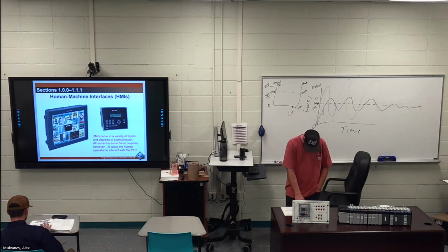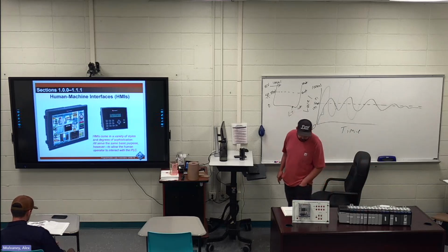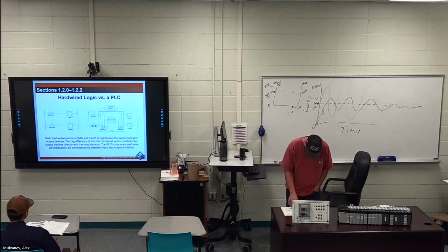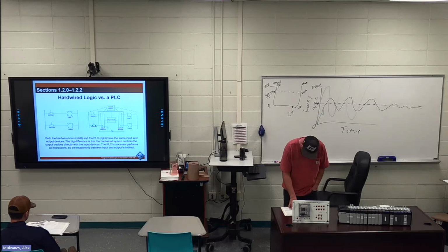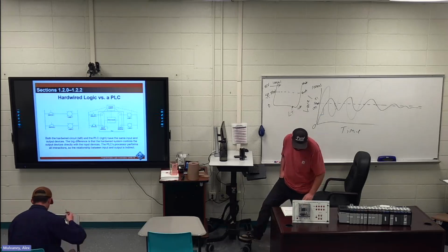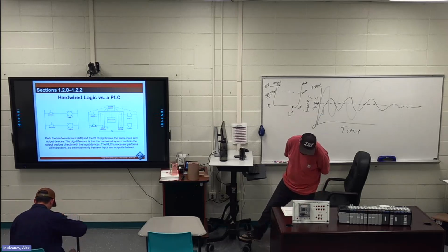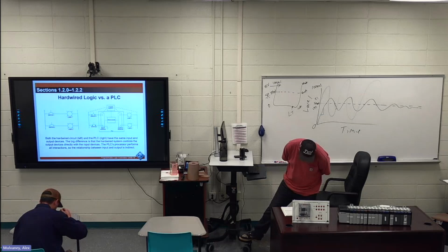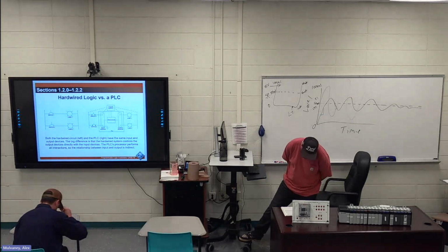122. PLC controlled circuit. Second sentence to the end, just about the whole thing. As you can see, the switches are not connected directly to lamps. Instead, they're connected to an input module. The rest of it is a separate highlight. The lamps are connected to an output module. The input modules and the output modules do not communicate with each other directly. Each is controlled by the processor.